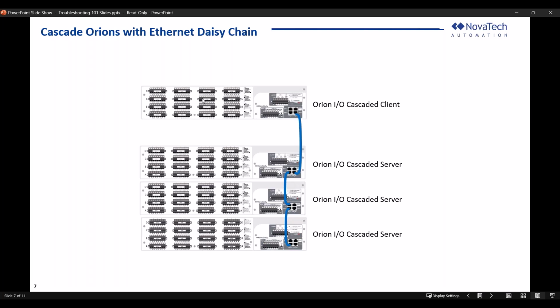I think this picture depicts an application where you have a lot of IOs, but you don't need to poll a lot of devices. An IO, just a reminder to everyone, can act as an RTU. You can enable master protocols on it using DNP or Modbus. The only limitation is a limit of 600 points, because an IO is not a true RTU.